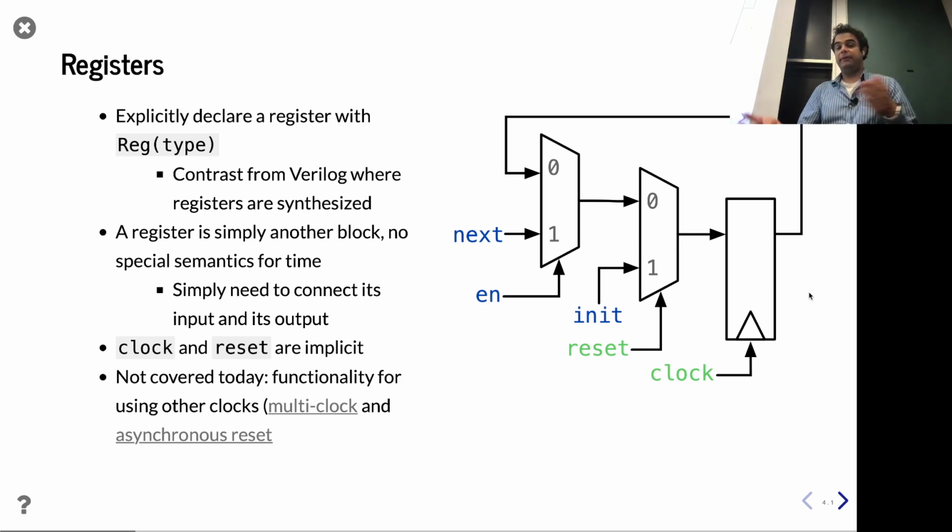Now, when you have a register, there are various bells and whistles you can have on it, such as a reset port or the ability to have a write enable. Depending on your technology library, there are different ways of doing it. On this diagram on the right, I'm showing abstractly and theoretically how it looks. In real hardware, these may actually not be muxes; they may be specialized registers.